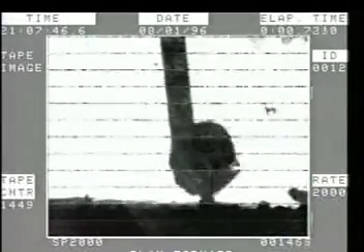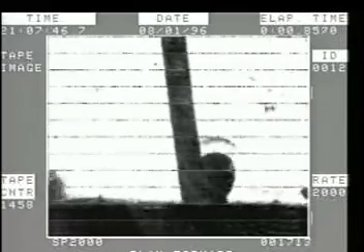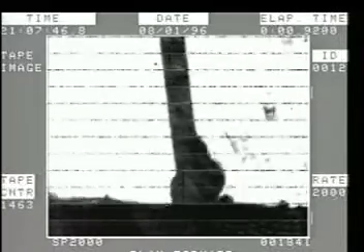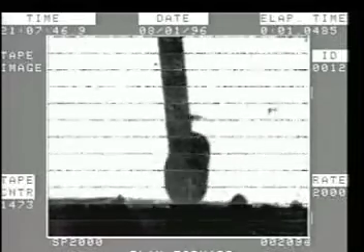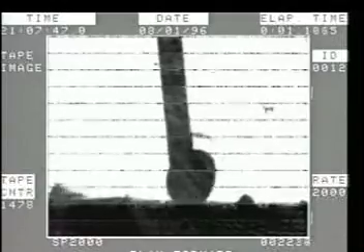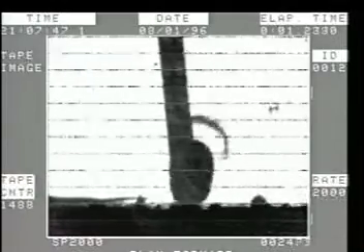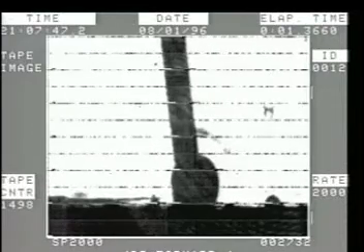However, when viewed up close, globular transfer exhibits extreme violence in the arc. The violence of the process is shown by the large droplet size. The arc is not forming anywhere on the droplet. A current density high enough to pinch off the droplet cannot be reached. Gravity and uncontrolled electrical magnetic fields dominate this transfer method. A droplet often wobbles around in space as it is pushed by the arc from one point to another.